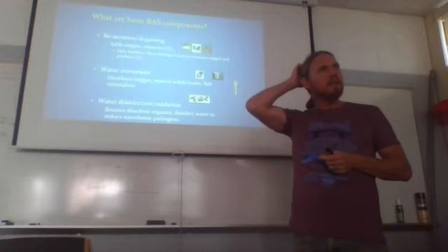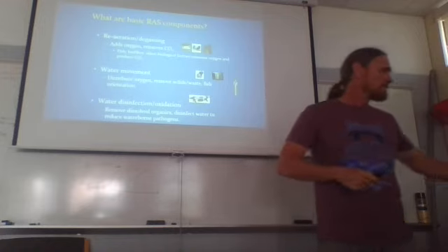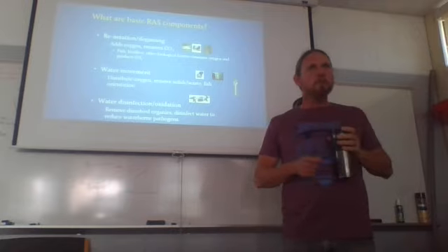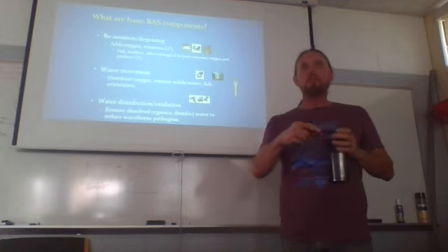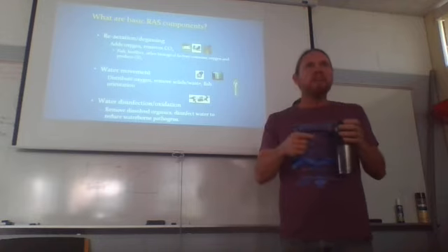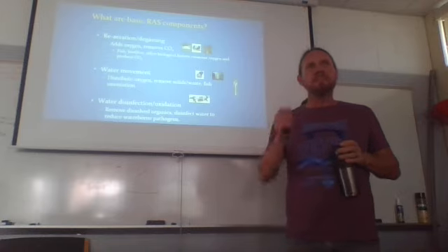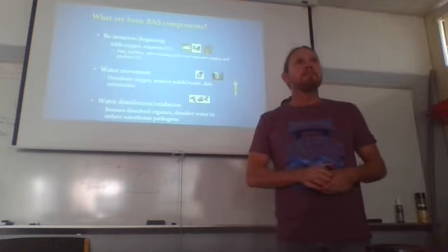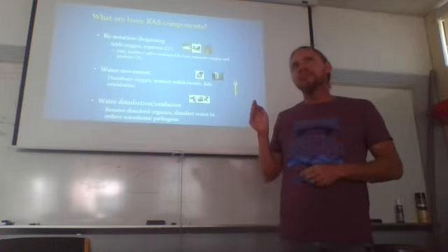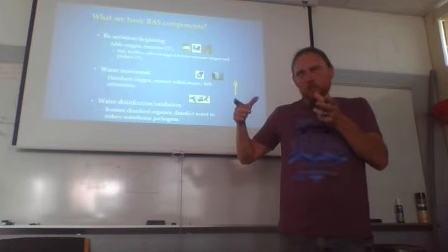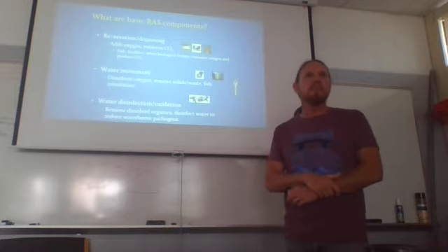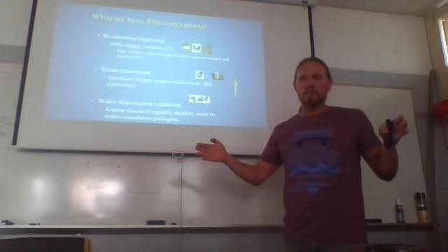Also, what else do we know about ultraviolet light and water? Ultraviolet light doesn't penetrate very deep into the water. So yeah, it has to be a narrow tube. And if it's something that's a little bit less flimsy than a bacterial cell or an algae cell, say a parasitic copepod, and it's not right next to the sleeve as it goes down that tube, it's out here a little bit, it might be able to get by. Some of the larger parasitic pests end up getting by. So another thing to consider is the contact time.